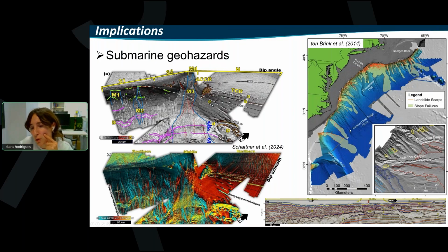In addition, the more sediment that we put into these systems, in particular under-consolidated sediments, which can reach very big thickness and which can have a lot of water in the pore content, the more it could generate slope failure, because you are creating a significant thickness and a significant gradient over these slopes. So contourites themselves, the sediment itself, can also aid in the generation of slope failure.